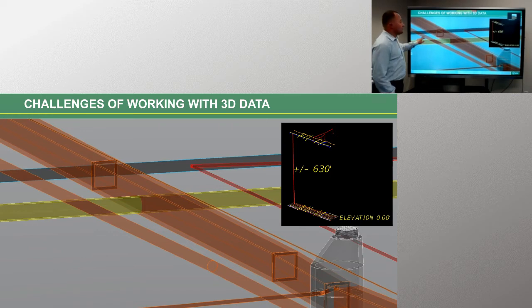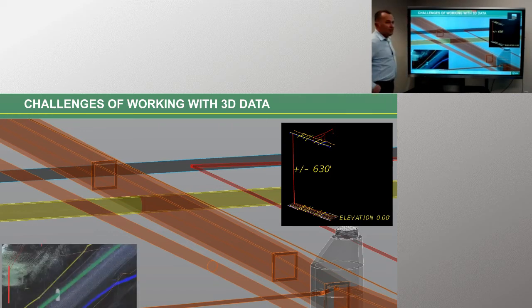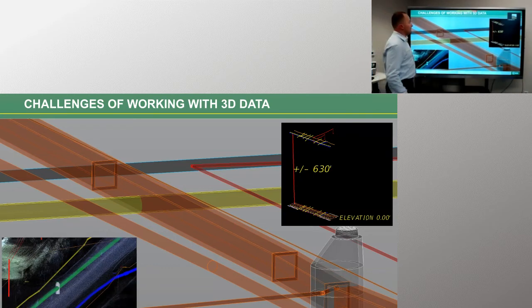Some aberrations in modeling might occur, where you can have kinks in the actual lines. Those you have to isolate. That also has to go through a QC process. And some of the egregious ones are actual conflicts that are based on depths that we gather from the field. And at that point, supplementing with quality level A test holes is highly recommended. Obviously, we can't have a gas main going through an AT&T duct as shown on this example.